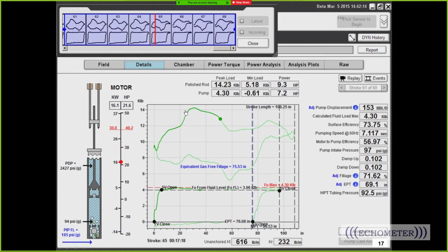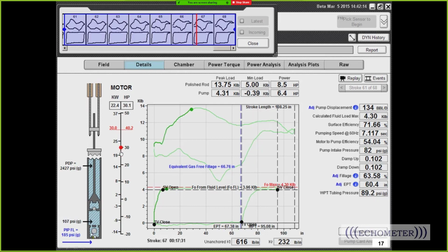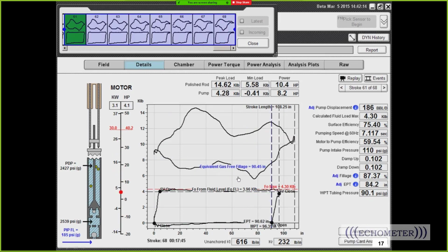Goes to a maximum kW right there, and it goes to a maximum kW right here near the minimum load. So the kW, this little speedometer here, is showing us the instantaneous kW during the pumping cycle, and it can tell you where the maximums occur, and typically they occur right about there near the peak, right up there near the minimum. But the torque factors have an impact on this, so it won't be quite the same as if the pump was full. We'll talk about that more.